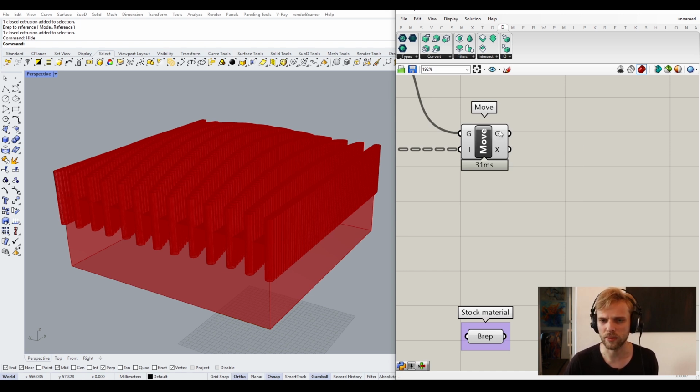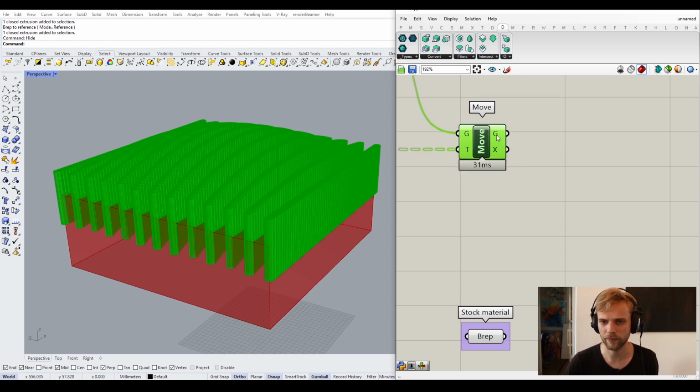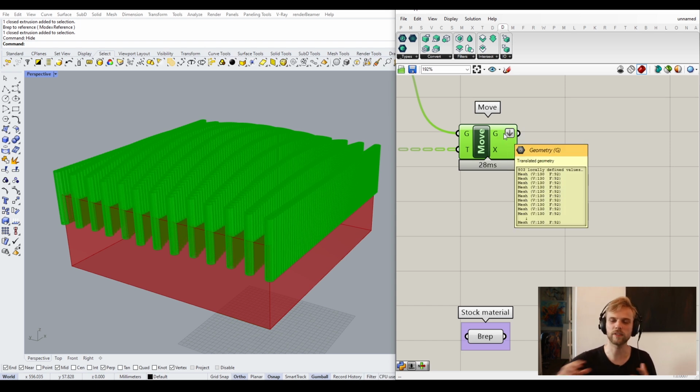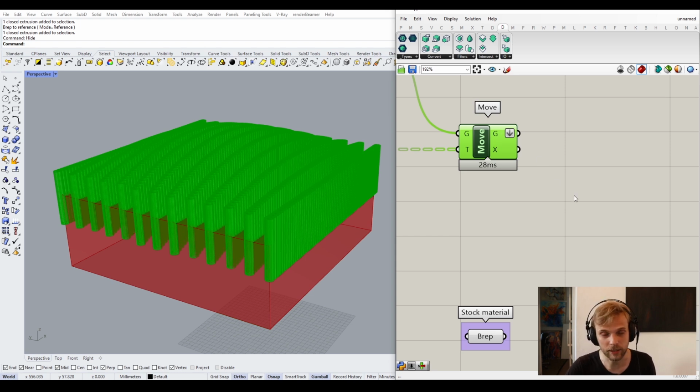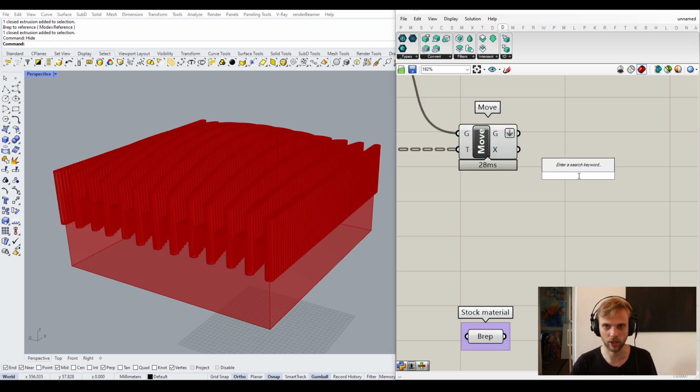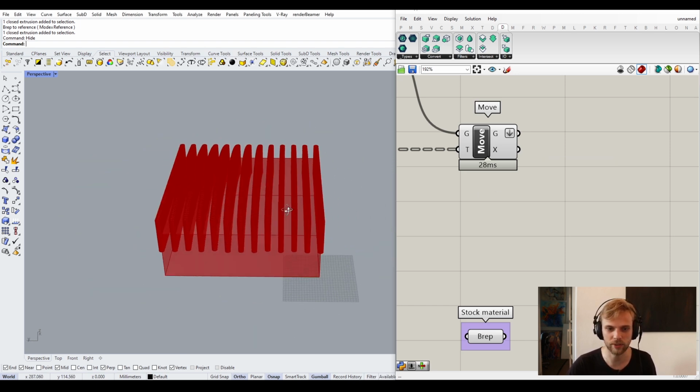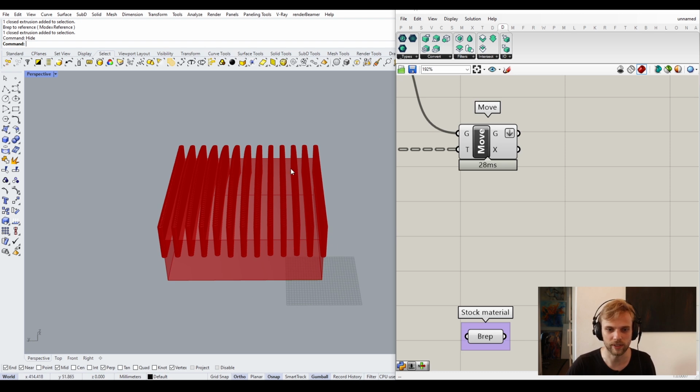I'm going to right click on the move output, the geometry output, and choose flatten. There we go. So now all of my meshes are placed into one big happy family, in one list. They were placed in separate lists before, because notice these rows? Each row was a separate list of meshes. By using flatten, we just said, no, all of them come in all at once.